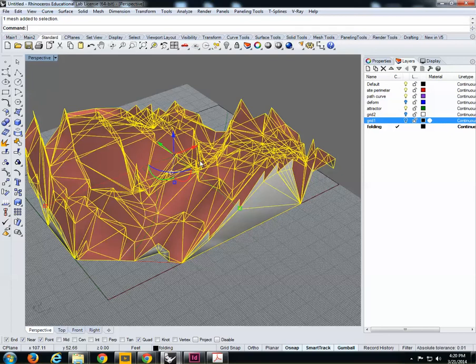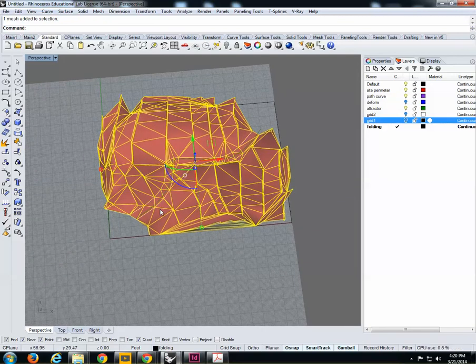Right, so Rhino works with both meshes and NURBS. But Genaro very well says that Rhino is better with NURBS for now. So if you want to do Boolean operations, you can do it with both of the different geometries, but Rhino will perform better if the geometry is NURBS. Also, if you want to make 2D, you have to do that only with NURBS geometries. Since our goal is to start visualizing that with diagrams, plans, make 2D command, then we better translate that to NURBS. The command to do so is mesh to NURBS.